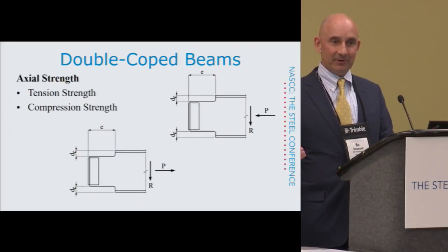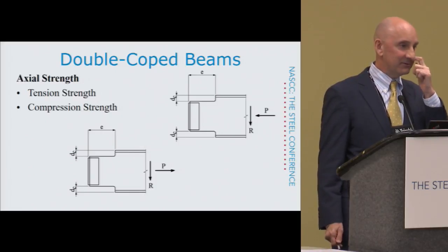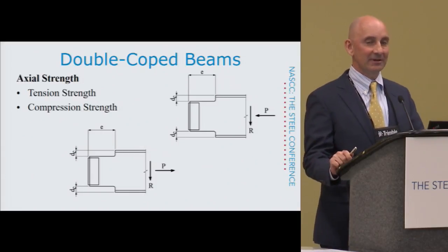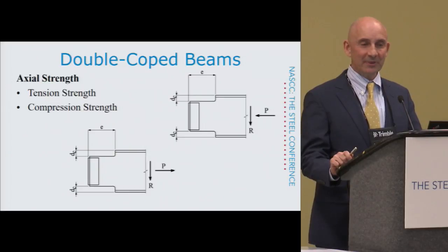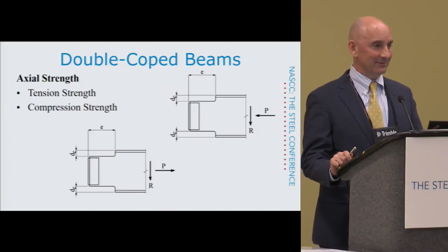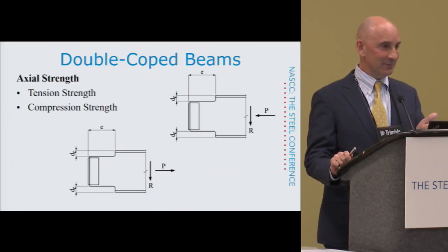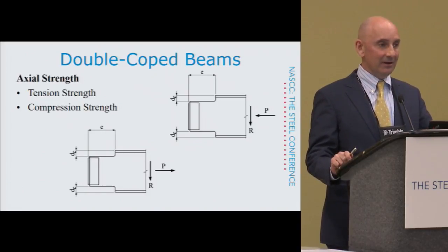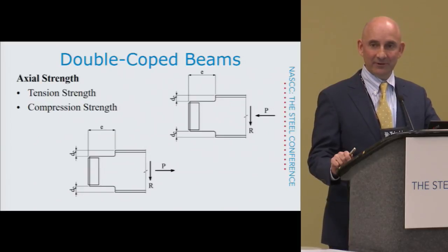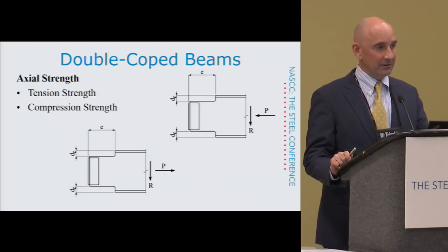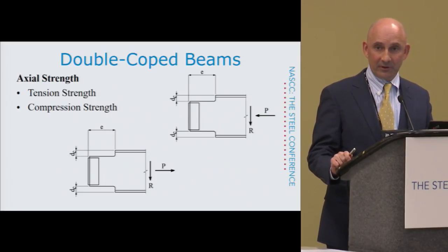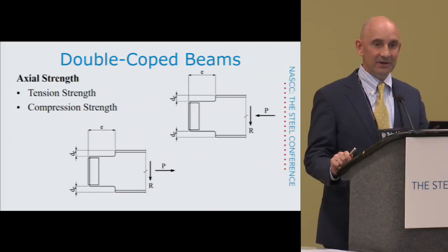Now, to combine with lateral torsional buckling, if you think of member design, say you have a W16 spanning 30 feet, and you want to calculate the compression strength plus the flexural strength combined, you would probably go straight to the spec, combine per chapter H, which is similar to what we've done, and then go to chapter F for the lateral torsional buckling, which is what we've done. We've gone to F11, and then for the compression, you would go to chapter E.